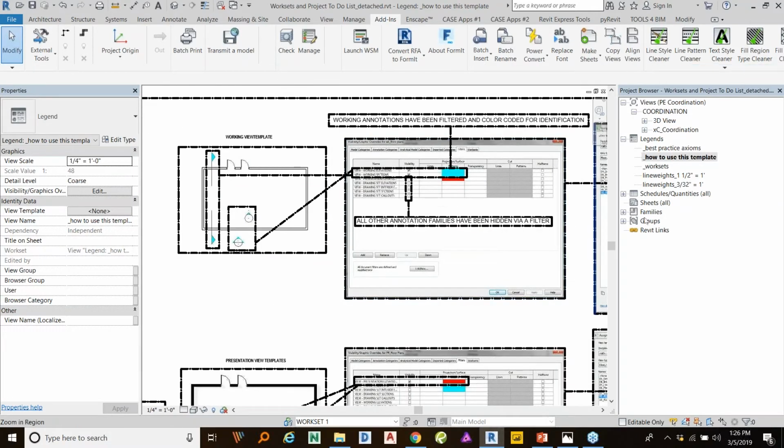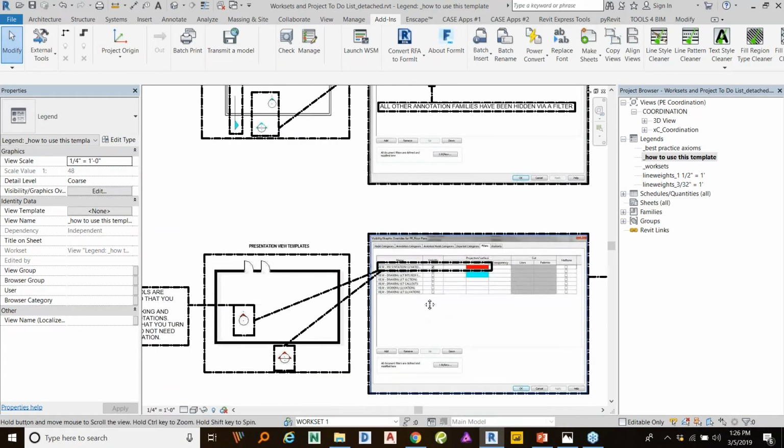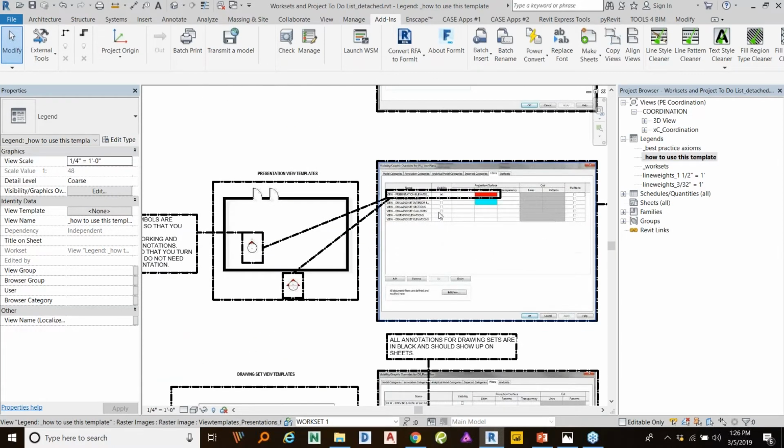So as you continue building your browser organization, the more of these filters you're going to have to create. I'm strictly dealing with it here in terms of the three mains, which I still think are probably the best way to go and the most efficient. And if you were to go in that direction, then you would basically have to create a Revit template for each practice area, which I also think is perfectly fine because all practice areas tend to be different.